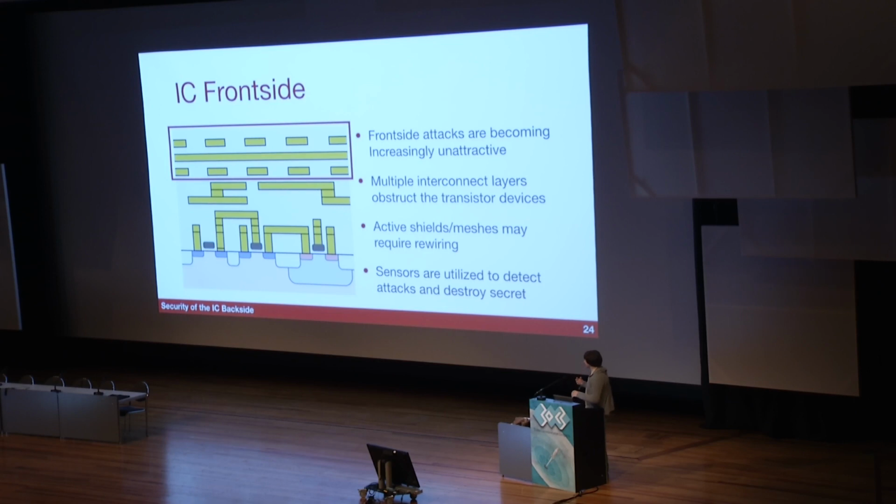And you can do other stuff as well. You can actually do sensors. Assuming that the density of what you have on top of the chip is so high, you can assume that no light will ever get through. So if you ever see light underneath this mesh, then you know that somebody opened up the chip. Stuff like that. And this is really stuff that is implemented on lots and lots of devices.